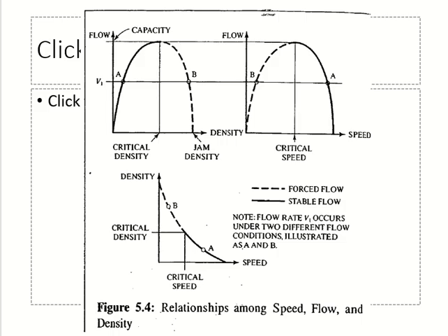Doctor, can you repeat? Which one? About the flow and the speed. So when there are no vehicles on the road, the speed will be very high, right? When the flow increases, that means more vehicles on the road, so your speed will decrease. So your speed is going down, flow is going up. The flow can go up to capacity. Can I add more vehicles on the road after capacity? Yes. That will be an increase in density. But these extra vehicles will block each other. So when they start blocking each other after capacity, the flow will decrease. So this is this region now.